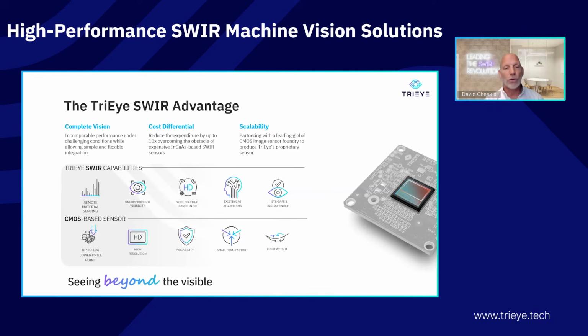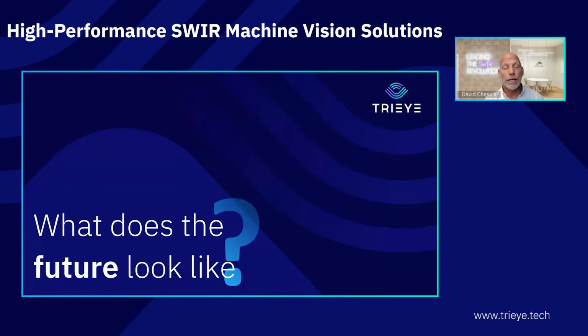And that allows us to do all these SWIR capabilities with remote material sensing, in all kinds of different environmental conditions, with a wide spectral range in HD, eye safe, and allows us to bring all those advantages of the CMOS-based sensor, which is the low price, the high resolution, manufacturing reliability, small form factor, and light weight. And that's how we are able to take advantage of these two capabilities and deliver this SWIR imaging on CMOS. So that's what we're doing today.